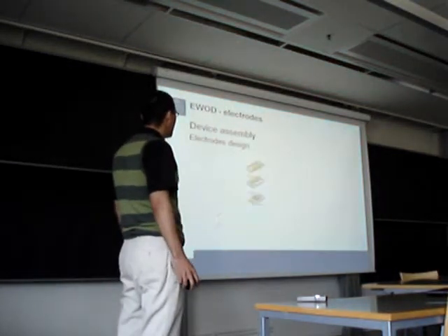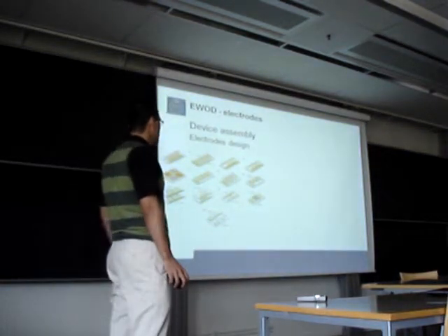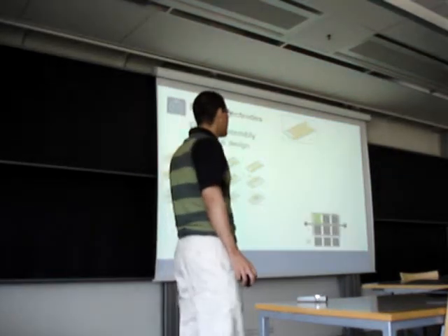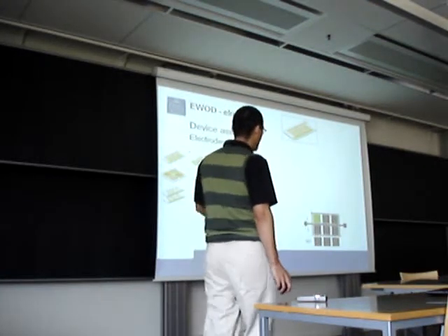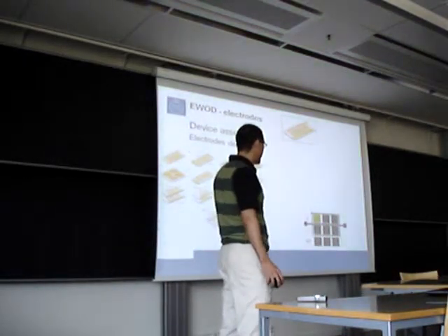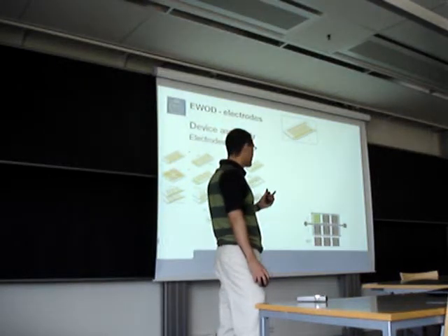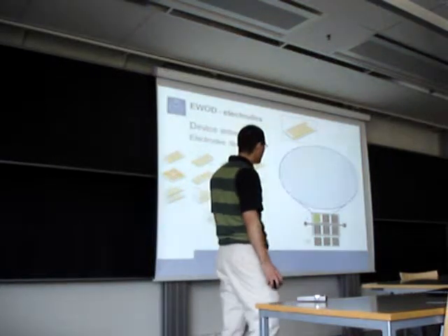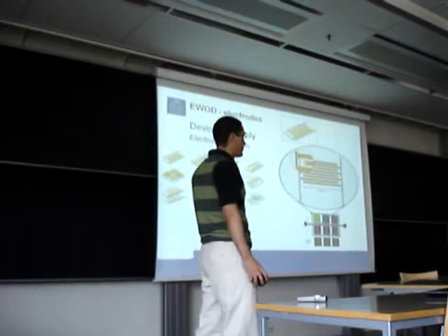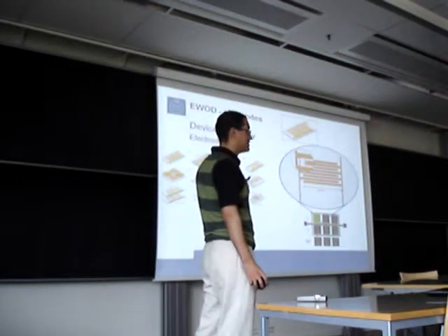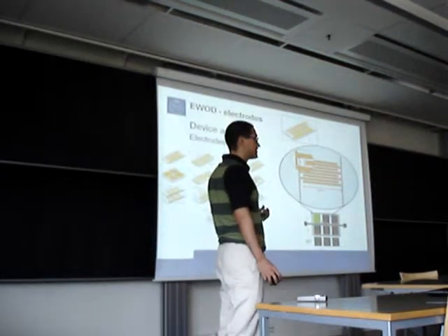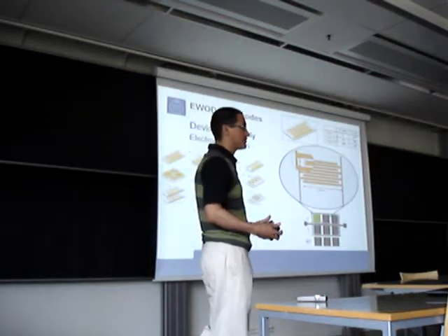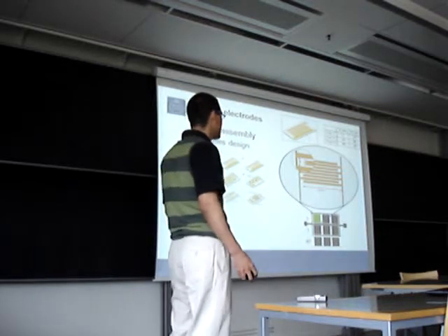So having that, I wanted to design my electrodes. There were a lot of configurations for it, but I took the best for our purpose. Then I created 9 cells. From the 9 cells, I have 6 that are connected to the potential and 3 that are going to work for negative control purposes. Inside each square, we can find an array of electrodes that I will change between chips in the size of the electrode and the gaps between them, to see how they are going to affect bacteria with these changes in size.